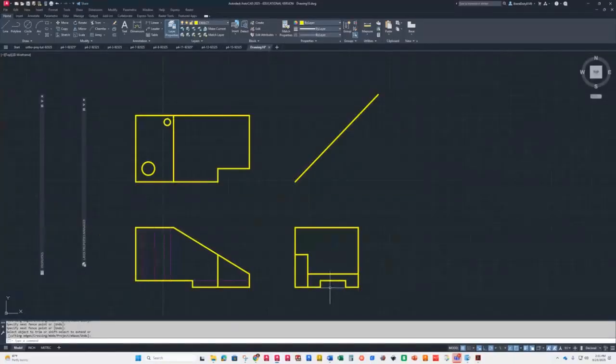All right. Now, you'll notice that this notch is here. It's 25 tall. Well, there's 25 difference between here. So when you look at the top here, there's actually some hidden lines that are missing. So we can actually project from here, up to here, and over under here somewhere. And then we can do the same thing here. Bring this guy up and bring this guy over somewhere in there.